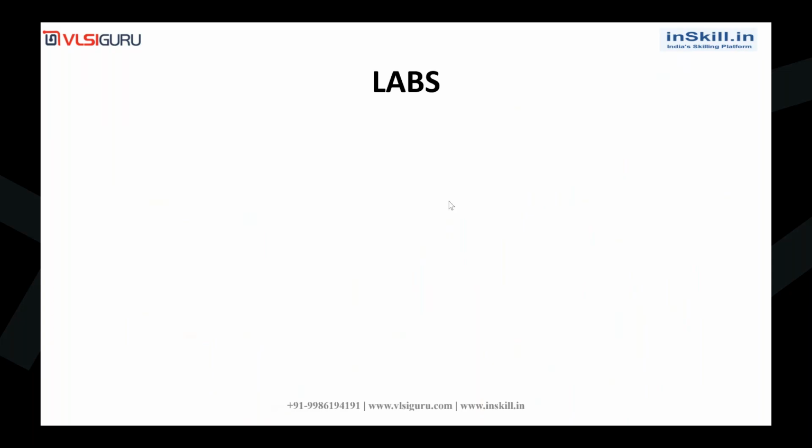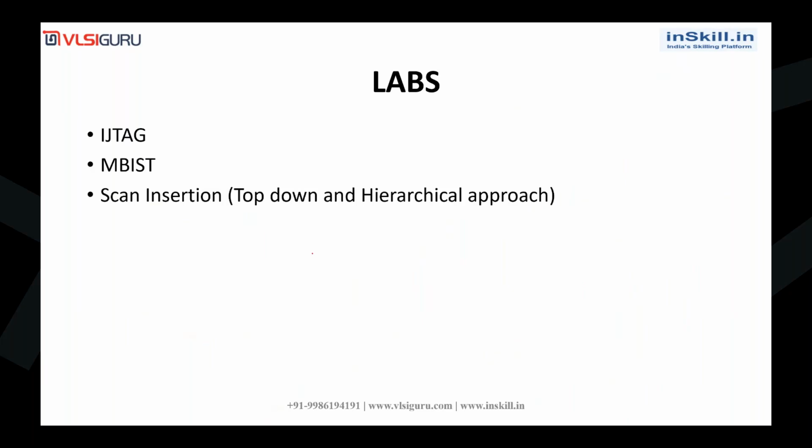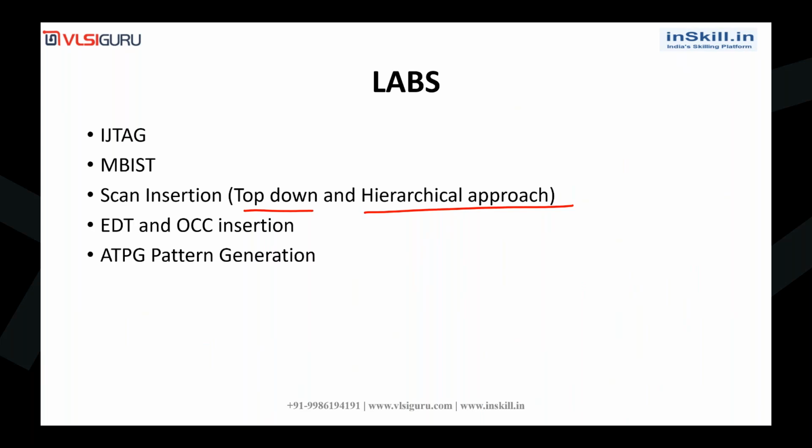So in our labs, we'll be covering JTAG insertion, MBIST insertion, and scan insertion. There are two approaches in scan: one is the top-down approach, and the other is the hierarchical approach. We will cover both approaches in scan. Then EDT OCC insertion, ATPG pattern generation, ATPG and MBIST simulation. Boundary scan we will be covering only in theory. So these are all the things we will be covering in our labs.